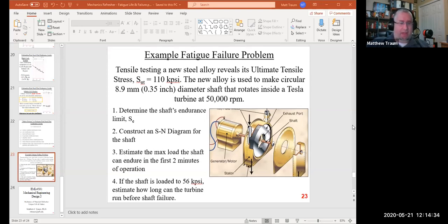So for example, if you've got a solar fired boiler, it's really difficult to do reheat with a solar fired boiler. So you end up with wet steam, and you can't generate power from wet steam with a conventional turbine, but you can with a Tesla turbine. I actually was an engineer at a startup company that did that. We had a commercial scale power plant that was a solar fired Tesla turbine driven power plant.